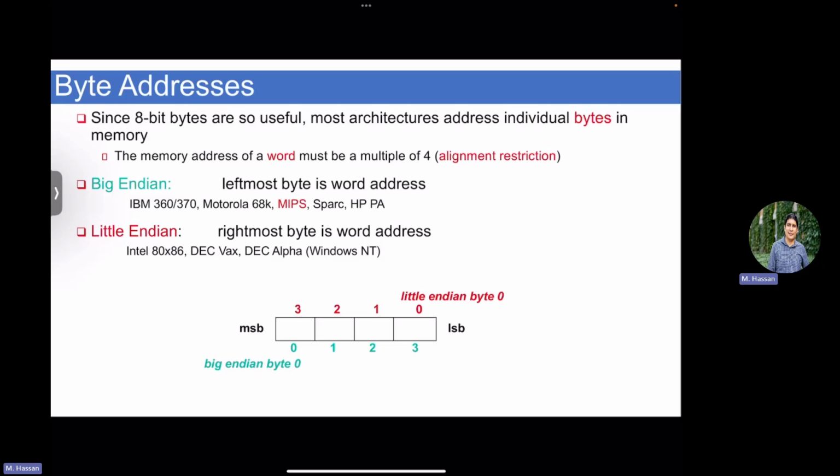Most of the time you say, it's already ready, verifiable, good cost, I buy it, and then I build the translation link, right? And you find most SoCs right now building a lot of translations everywhere, right? It's a practical consideration where modern SoCs are heterogeneous and they have different sorts of endianness, big endian and little endian. Okay? So it's important to understand what machine is which and what you are reading from the memory.